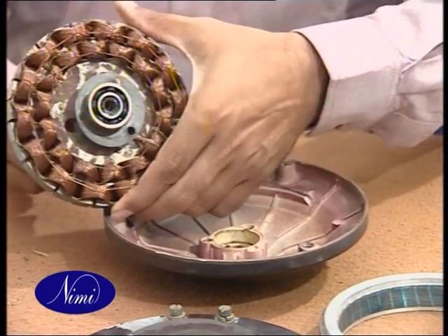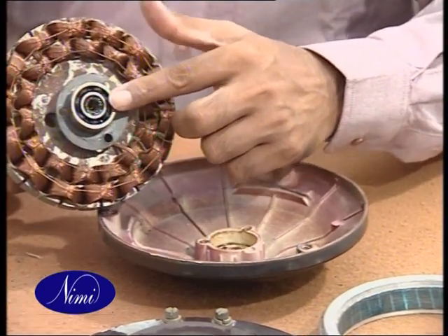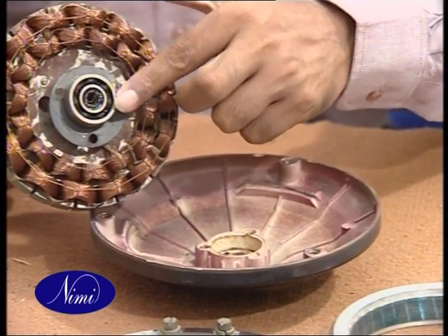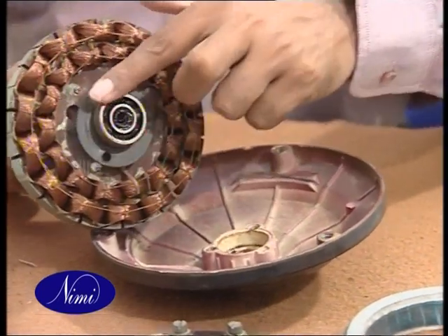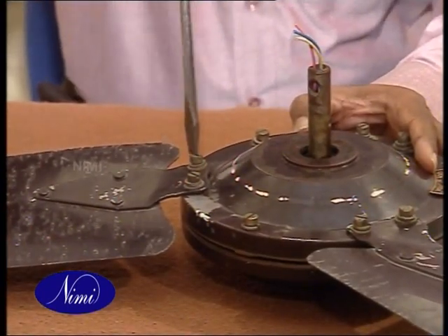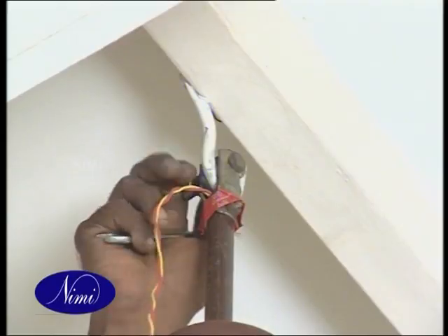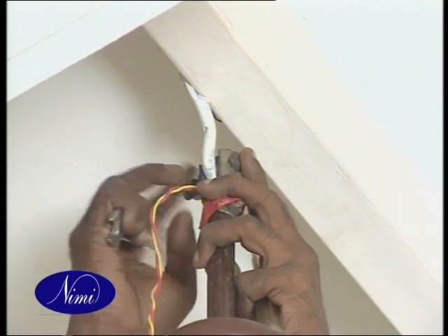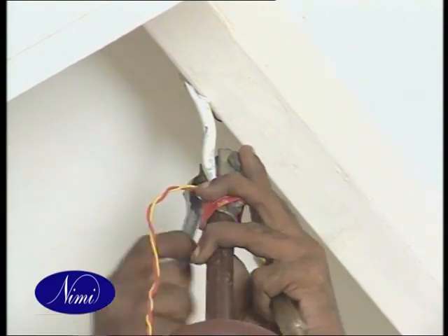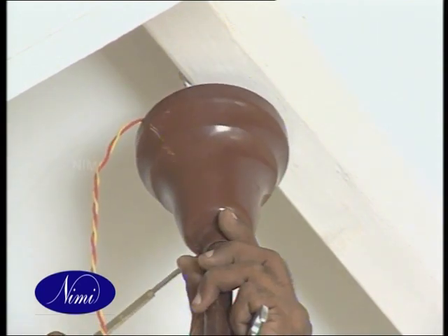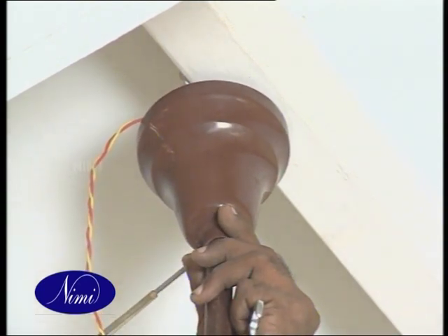The rotor and the blades are freely rotated with the help of ball bearings or bush bearings which are housed in the top and bottom cover of the fan. The blades are fixed on the top cover using fixing screws. The entire unit is then hung from the ceiling with a suitable pipe threaded on both sides and tightened with suitable check nut and a cotter pin to lock it in its position.